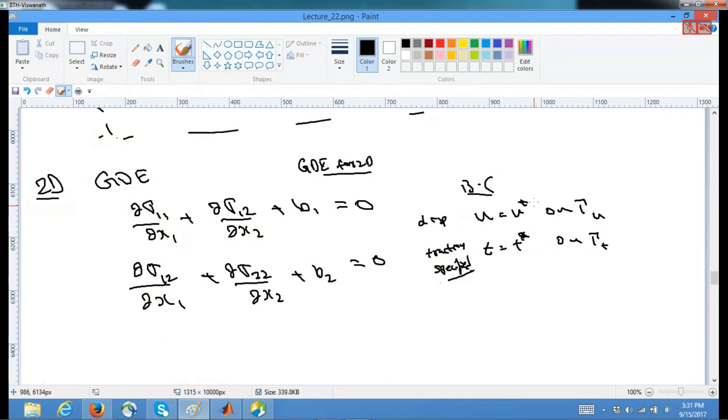So now what we need to take is, as we already know, in finite element methods we cannot start with a strong form, because the governing differential equation is also known as the strong form. We need to develop the weak form. The weak form we can develop in several different ways. Starting with the governing differential equation as it is would pose a little bit of difficulty in solving. So what I will do is propose something called the principle of virtual work.